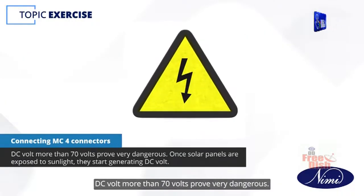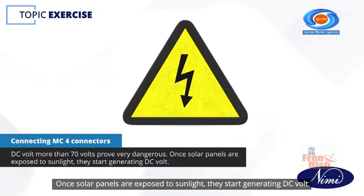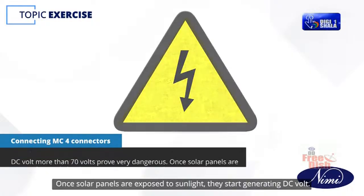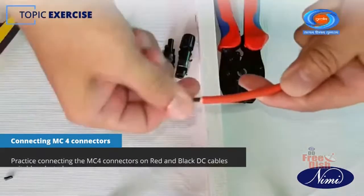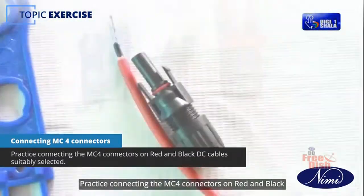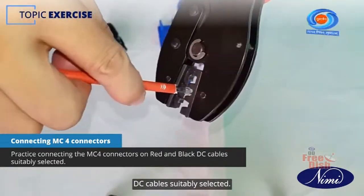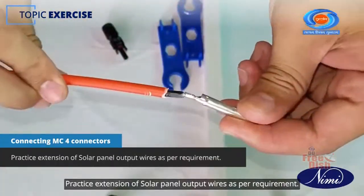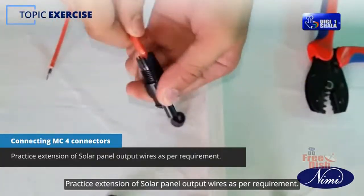DC voltage of more than 70 volts proves very dangerous. Once solar panels are exposed to sunlight, they start generating DC voltage. Study the pictures to familiarize yourself with assembly parts of MC4 connectors. Practice connecting the MC4 connectors on red and black DC cables suitably selected. Practice extension of solar panel output wires as per requirement.